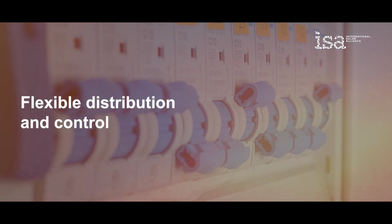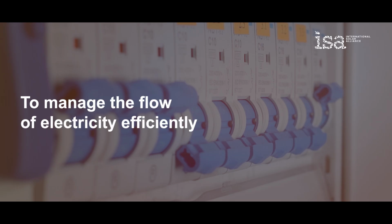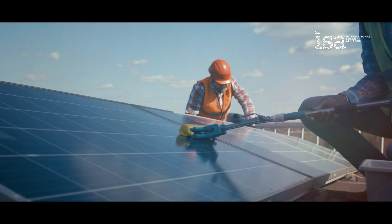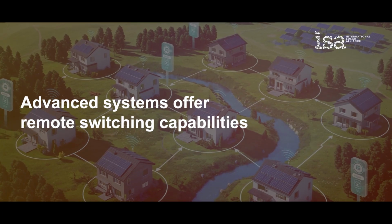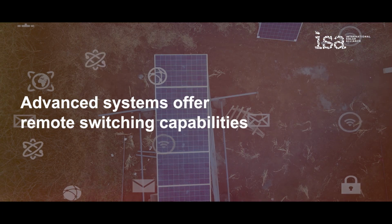Flexible distribution and control. Switchgear allows operators to manage the flow of electricity efficiently. In large solar plants, it can be used for sectioning the medium-voltage (MV) system to minimize power outages during maintenance. Advanced systems offer remote switching capabilities, giving grid operators better control over power flows.